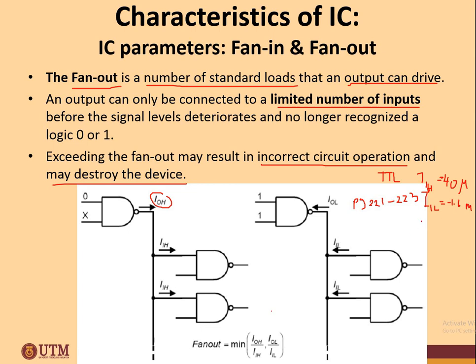How about IOH? IOH is 400 micro, okay, and IOL equals negative 16 milli, okay. So now let's say we want to see the fan out. I just use abbreviation, okay, because I don't have much space, but I hope you understand.